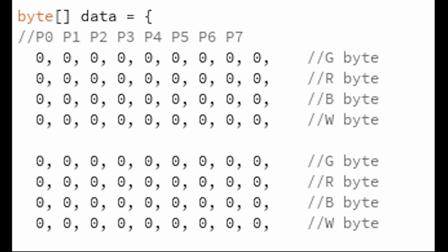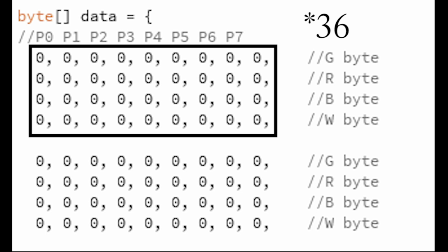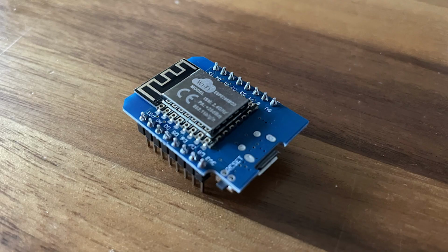Each column represents the pin number it transmits the data to, with the delimiting 0, and the 4 rows are the 4 color bytes transmitted. So, the color data of 8 pixels are represented in this 32-byte block. Other MCUs like the IoT-capable ESP8266 could also act as a more portable serial transmitter to transmit all the color data, but for now, a processing sketch shows the proof of concept.